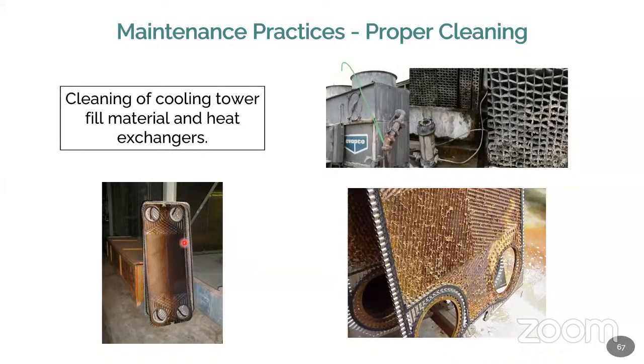You can regularly clean the cooling tower. These are the fins. You can take the fins out, and this is called refurbishing. You can take the fins out and clean them, because water fouling will always take place. Possible, you can see, it is something like that. So it should be very regularly cleaned with the help of compressed air or by using some other mechanism.